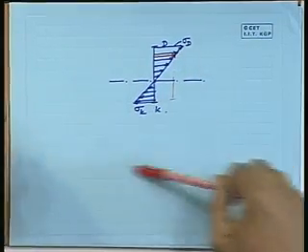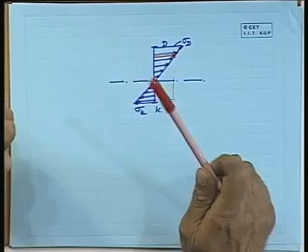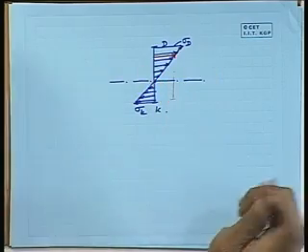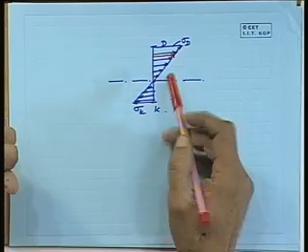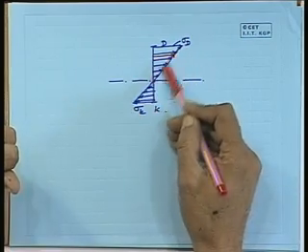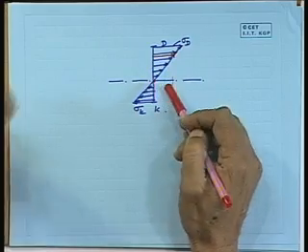So this analysis is required so that you can make an assessment of which portions of the structure can be of high tensile steel. After all, that is much more expensive than ordinary mild steel. There is no point unnecessarily using mild steel for the entire region where the stress level is not going to exceed the permissible stress limit of mild steel itself.